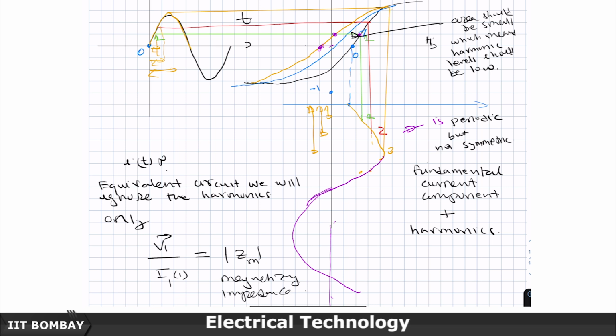Plus you also know that because the iron is a good conductor of electricity, there is eddy current loss which happens along with it, and because of it we have to laminate the core. These are things I have discussed earlier when I discussed eddy currents and hysteresis losses.